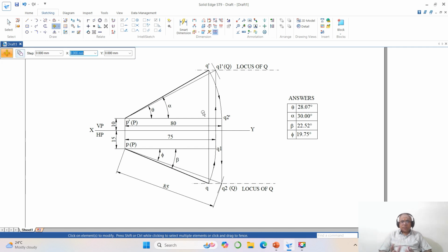Once you get that, you transfer the line: the Q2 which was parallel to HP, you make that also inclined to HP, and the Q1 which is parallel to VP, you also make inclined to VP. So this is your final takeaway, wherein I will be able to create the drawing without looking into the solution. And also the accuracy of the drawing is up to the second decimal point, which is quite evident from the drawing I have done here, and also the solution I got from this. Both are one and the same. Thank you.